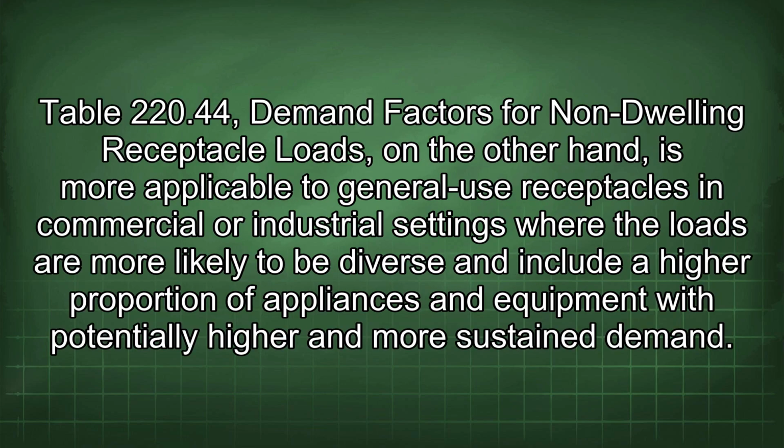Table 220.44, demand factors for non-dwelling receptacle loads, on the other hand, is more applicable to general use receptacles in commercial or industrial settings where the loads are more likely to be diverse and include a higher proportion of appliances and equipment with potentially higher and more sustained demand.